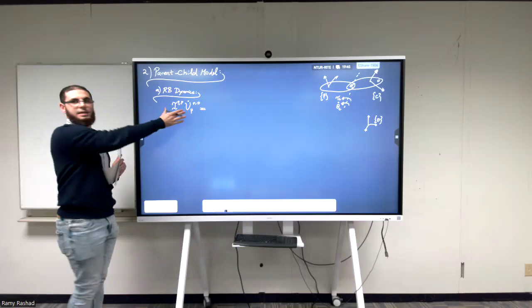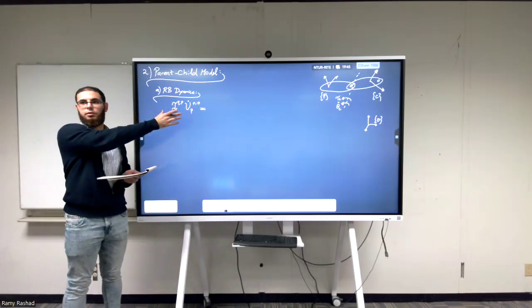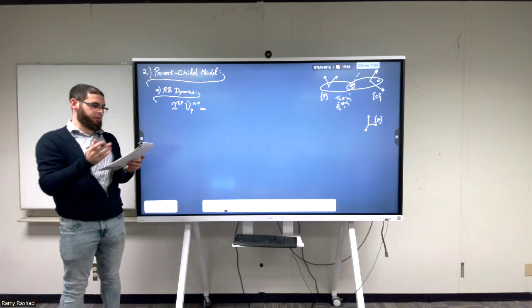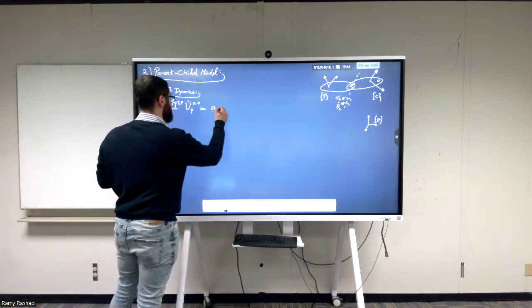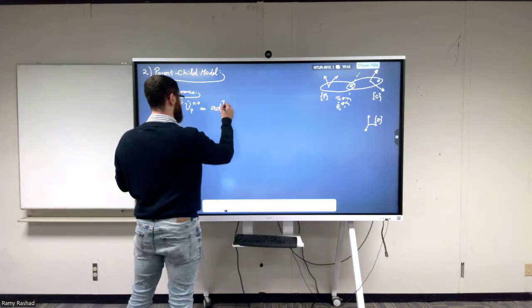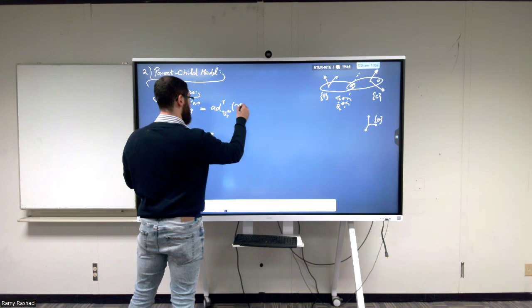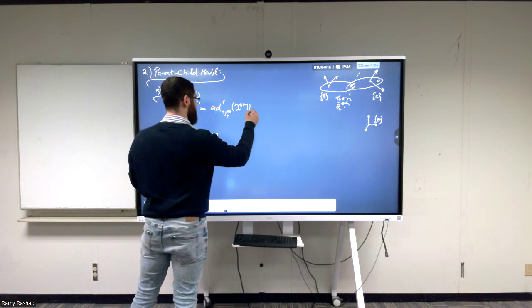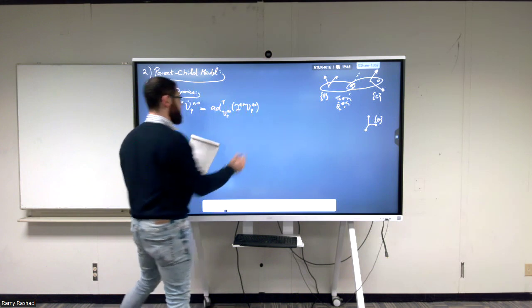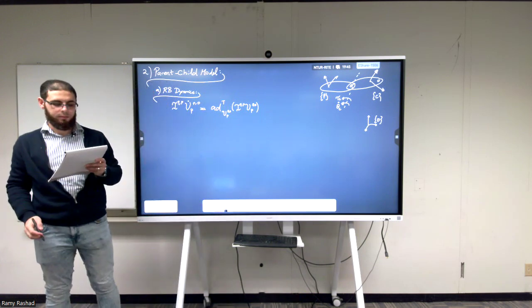So this term is the rate of change of the momentum in the body frame. We had the adjoint term, which had a combination of all gyroscopic and Coriolis effects, which is this one.